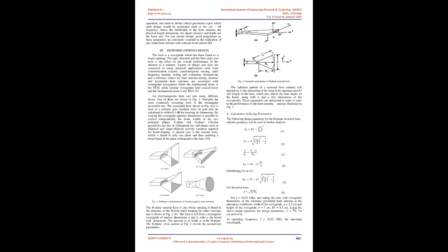When one considers a waveguide without a horn in operation, the sudden interface of the conductive walls or free air, as the case may be for interception or transmission of microwaves, causes an abrupt change in impedance at the interface. This often results in reflections, losses, and standing waves. Also, when the flare angle becomes too large, as it tends to 90 degrees, the operation tends to assume that of a hornless antenna, thereby resulting in losses, reflections, and standing waves.